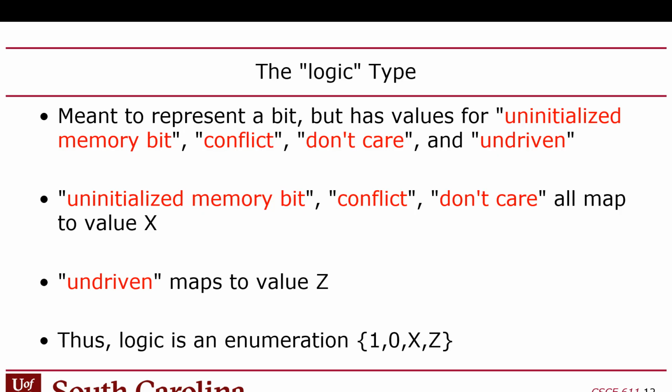Now, in an actual circuit, if you have a memory element and you don't initialize it, it's going to be random. It comes up as a random value. When you power up a chip with a bunch of flip-flops on it, those flip-flops are going to be randomized. On an FPGA, you get to cheat a little bit, because when you configure it, you're actually initializing everything on the FPGA during the configuration process. So after you program it, you know all the memory elements are going to come up as zeros. But on an ASIC, like a regular chip, memory comes up randomized.